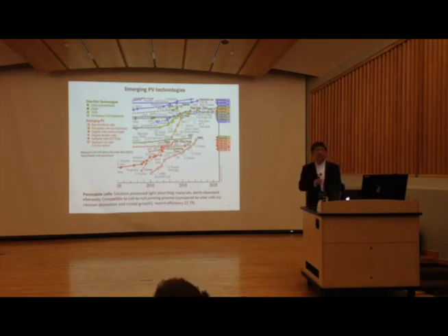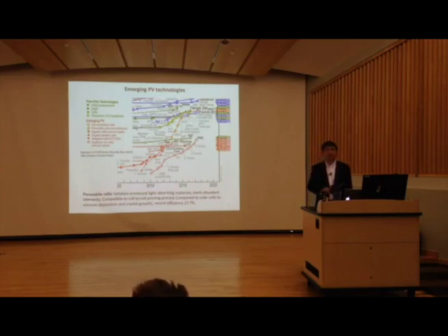So there have been quite a bit of alterations to the electrical code to address some of the issues there, in terms of rapid shutdown requirements, whereby the fire department can very rapidly shut down the production of the array when they reach a site.